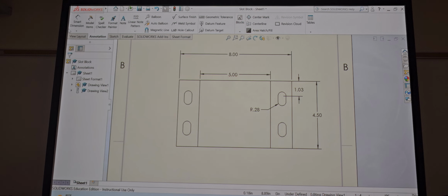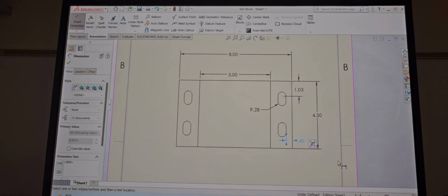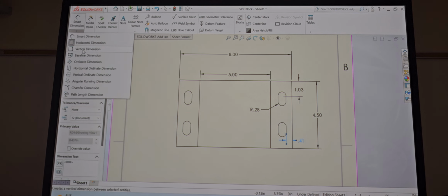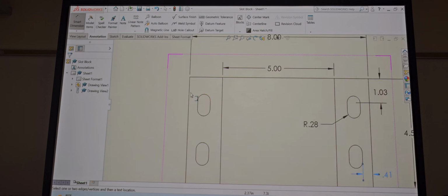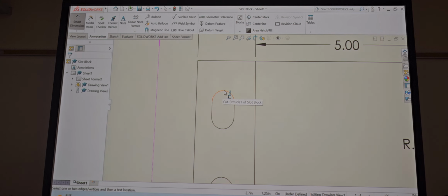So if I don't have it, I can use my smart dimension. From here to here, boom. Now I have it down here as my 4.7, right? And the other number that I need is the 4.4375. So if I click here, I scroll into it. If I can't hit the top, so, see how it took it in the middle, right? It didn't take the top.